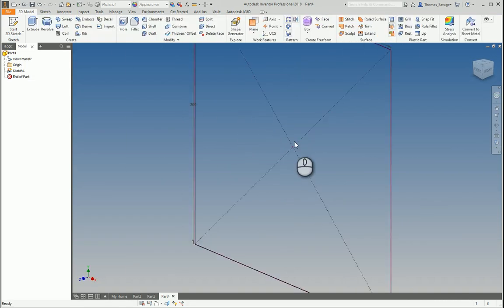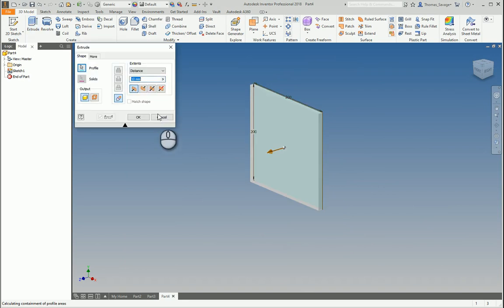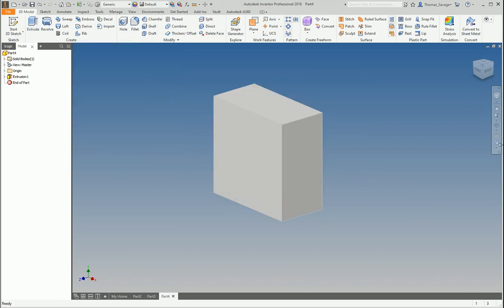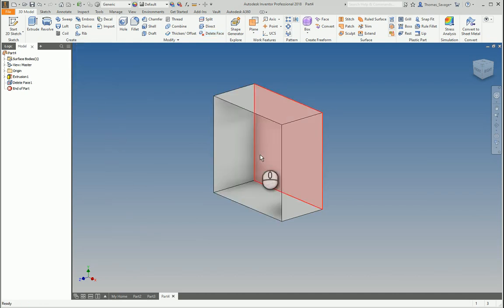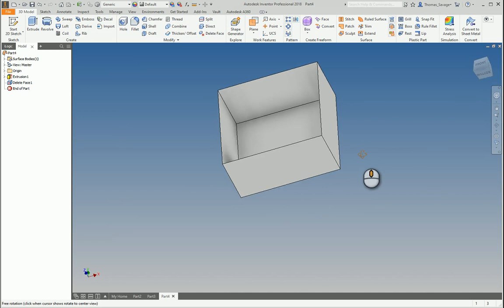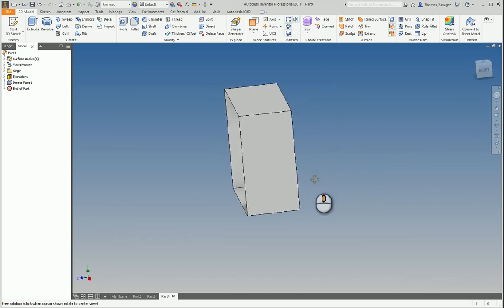So I'll extrude a square again by 100. It's one of the features where it's useful when I'm creating a model, and it can be very useful. But just to show, sometimes you could think, oh, that perhaps wouldn't be that useful. So it will delete either a face or solid, or lump or void. So if I click on face, okay, it deletes the face of that solid.